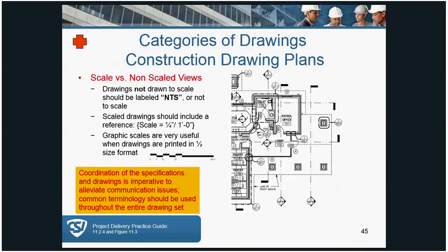Non-scale drawings and details need to be labeled "not to scale." Again, the drawings and specifications need to be coordinated. The drawing materials labeled must be consistent, and materials and products shown must also be included in the specification.